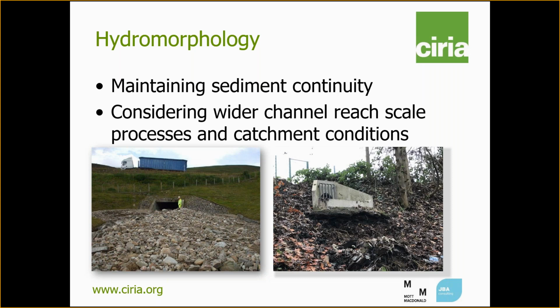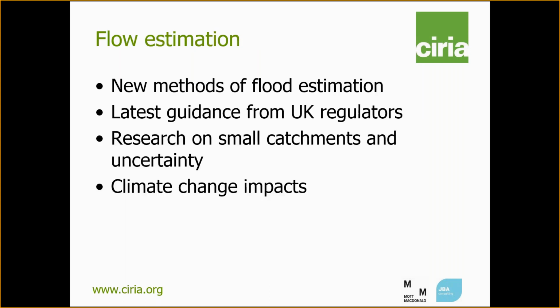So locating a structure where there's a low risk of outflanking, keeping a culvert length to the minimum, avoiding large changes in velocity which could lead to turbulence and scour, and minimising the need for future sediment removal, which has an added benefit of keeping the whole life cost down.